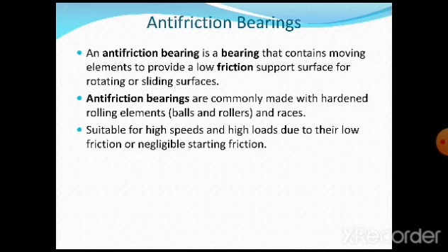Again, there are various types, like the deep groove ball bearing. In roller bearings you can have cylindrical roller, tapered roller, etc. That depends on the specific machining application, load carrying capacity or speed requirements. So we need to understand the basic types of bearings which are commonly used, with a brief understanding of their working.